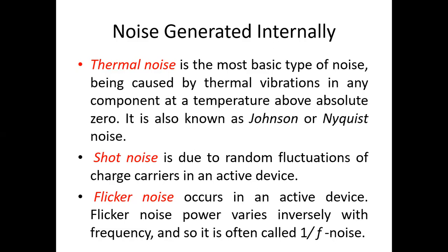But in a wireless receiver circuit, you work with very low power. I mean, the desired power is very low. In the air, the power level is already low. You catch from there as much as you can. The antenna cannot capture the whole power intercepted onto it. So eventually at the circuit, you get very, very, very low power. Now the small noise power can be significant compared to your received power, the desired power you have in the circuit. So this is why you need to take noise into account.